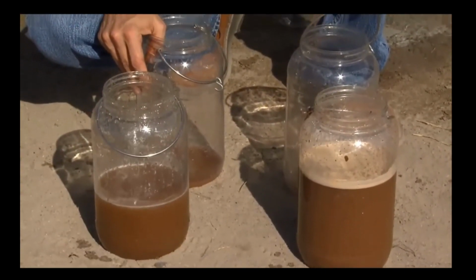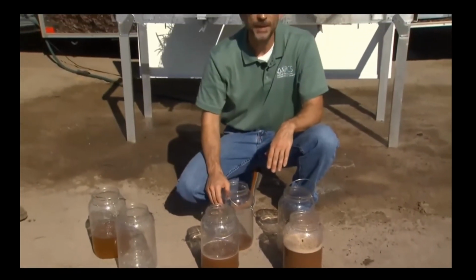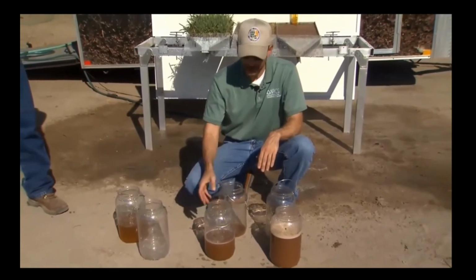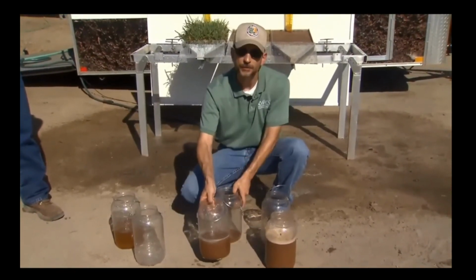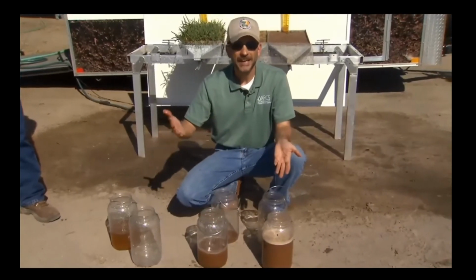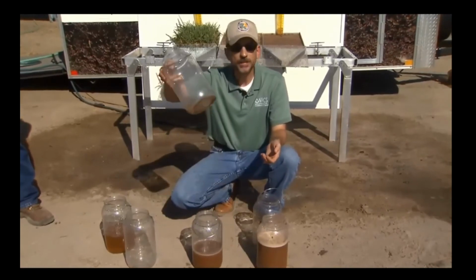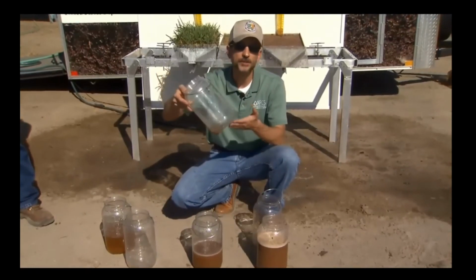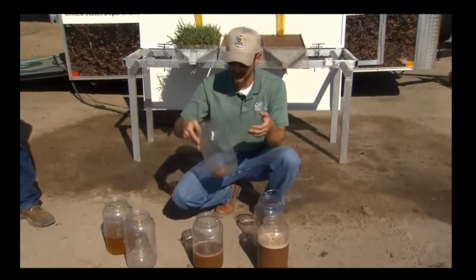And those very small particles, instead of being dislodged and blinding off those pore spaces that allow infiltration, allow the water to slowly infiltrate. And again, you do have some infiltration. This is kind of in between. It's okay, but it could be better. And you can see there is some flow through into the system. This is water that you're banking for later on, and this is your water storage capacity.